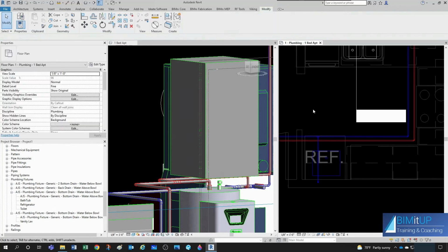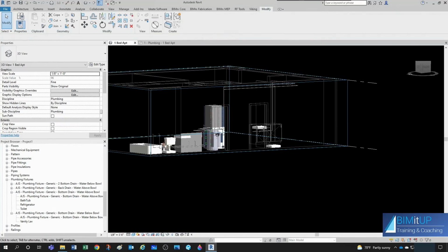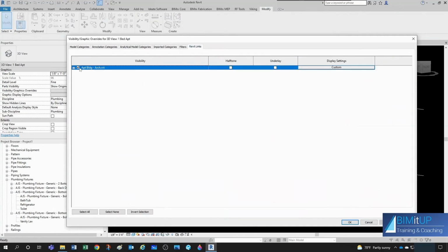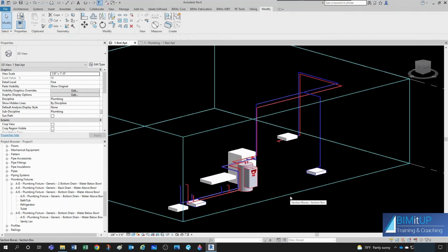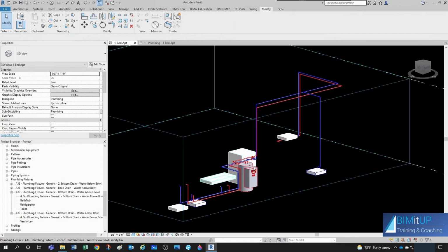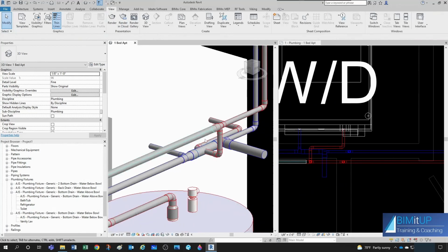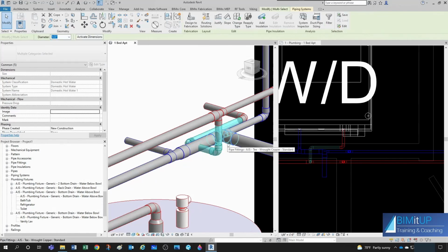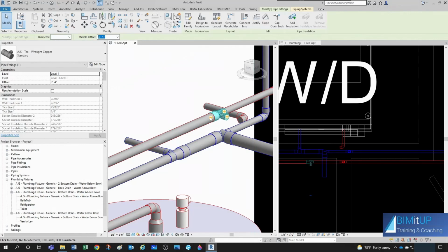So now let's actually untile our window, and let me take out my Revit link for a minute so you can see that everything has been properly piped. Now the only thing left to do is to check that our system is flowing our fixture units correctly. So let's check that out. But before that, I realized we have a little thing going on here. We have our hot water and cold water crossing each other. So let me get rid of this piece of pipe and then simply, actually I turned it the wrong way.